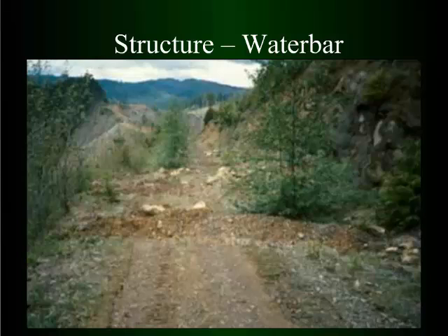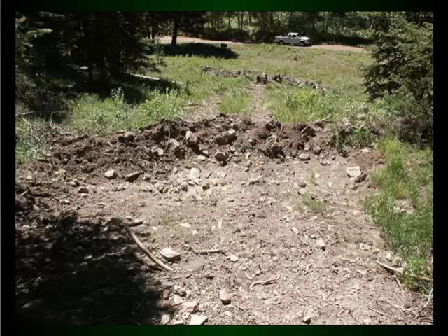This one's a little out of focus, it looks like. This is a water bar across the road that obviously is a road closing type water bar. It's not a drive-through. This is on a skid trail. It looks like it is down into the native soil a little bit here, and it looks like it's open. It's angled a little bit and open at the bottom, so it will drain out.